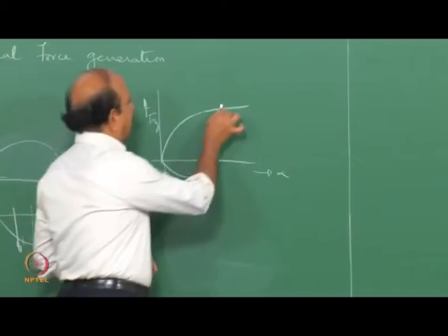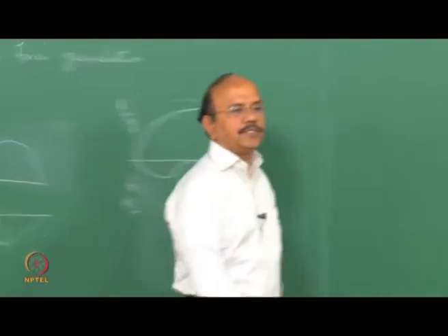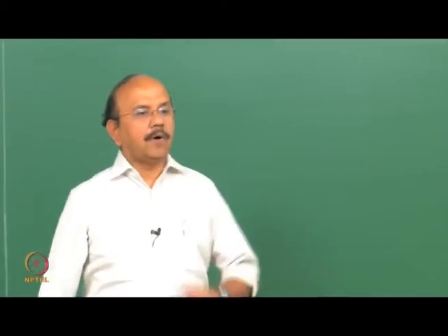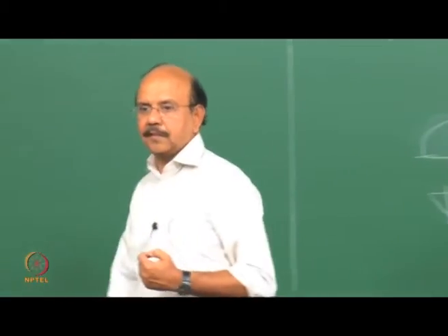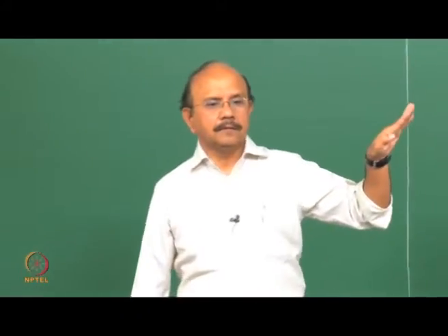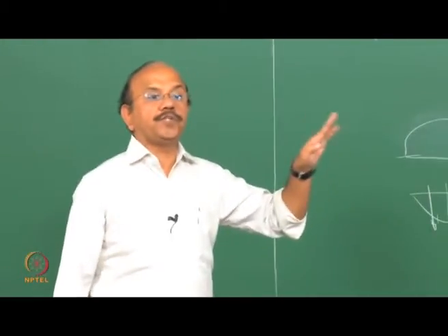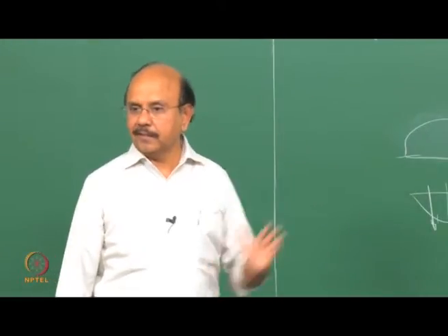In other words, where all of them have reached mu qz, the maximum force that can be delivered by these bristles, the resultant force position shifts towards the center, and the trail goes to 0.